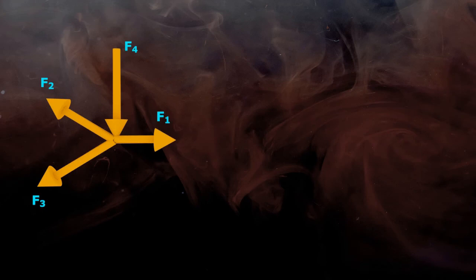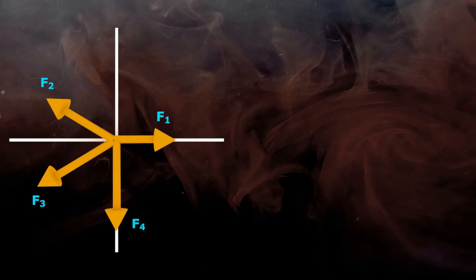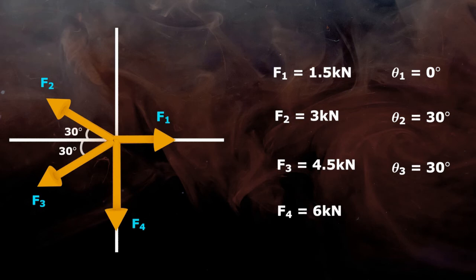So this is the free body diagram with all the forces along the x and y axis. Rearrange the forces so that all of them meet at the center. Now let's have a look at the given data. F1 is 1.5 kN, which is acting along the x-axis. F2 and F3 are 3 kN and 4.5 kN respectively, which make a 30 degree angle to the negative x-axis as shown here. And F4 is 6 kN acting in the downward direction along the y-axis.